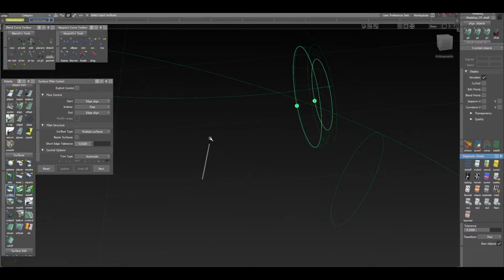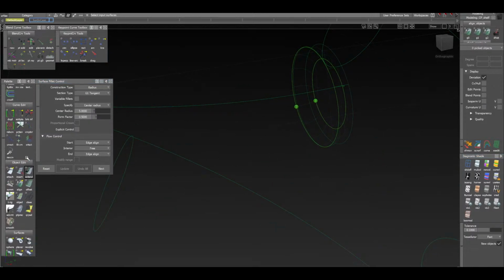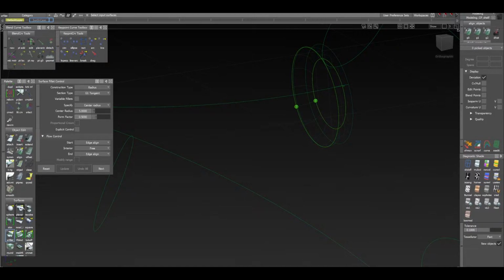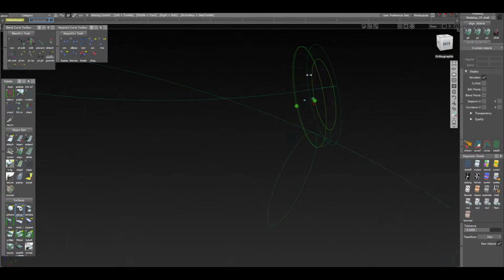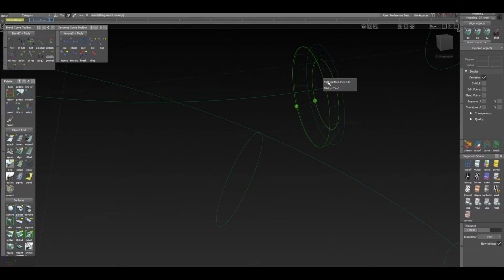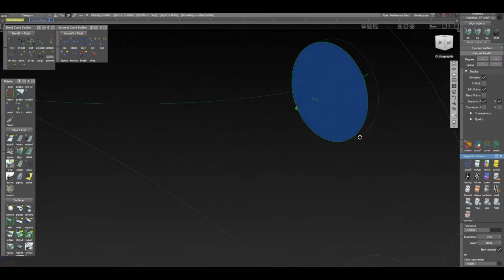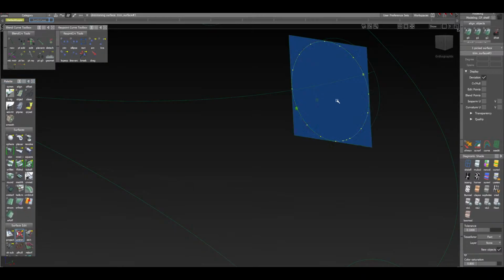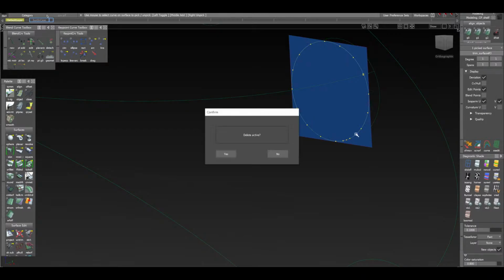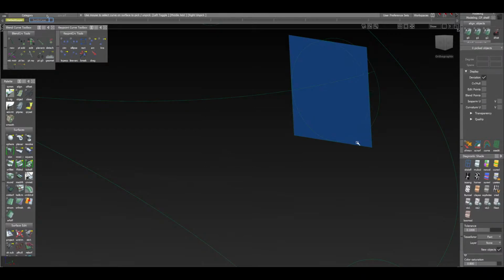So going back to X-ray mode now, and I'm going to move over to planar. I'm going to hit the base of that fillet. Okay, hit go. And you'll see that we have our planar. I'm going to untrim. As a matter of fact, I'm going to get rid of the curve on surface. So I'm going to hit Control Shift, pick curve on surface, left mouse button, and delete that. Okay.